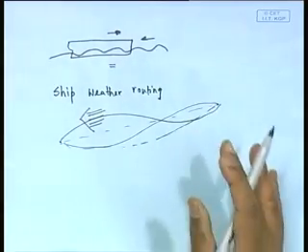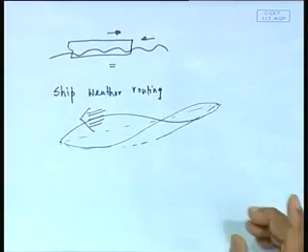But what is the resistance? It is only from the waves, maybe from winds also if there is a wind field there, but primarily waves, which means added resistance becomes a significant criterion for selecting which way you should go. We also talk about added resistance conversely, because a typical ship has a certain power and you cannot power up more. You are at full MCR rating, so you are making 16 knots, but because of waves you end up making 14 knots. So, we can look at added resistance also as a reduction in speed rather than an addition of resistance.